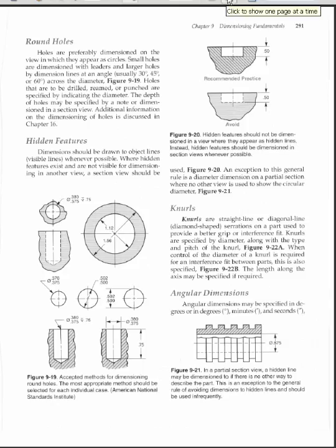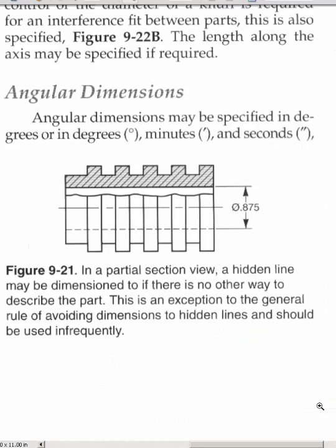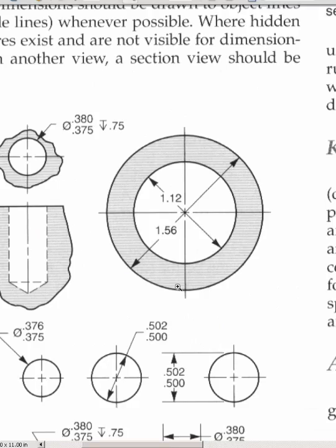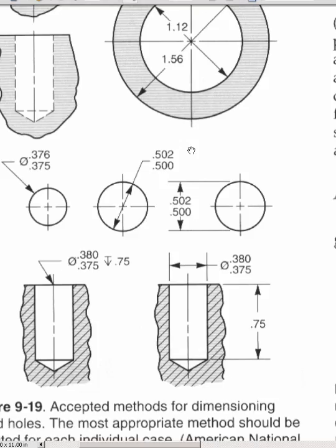However, if you're going to have to dimension something that's a hidden line, you can do it in this format: a partial sketch section that actually locates a dimension based off a hidden line. So, rule number 1 with hidden lines, don't dimension to them. For example, none of this, here's the hidden, nothing dimensioned. Down below, there's the hidden stuff, not dimensioned.